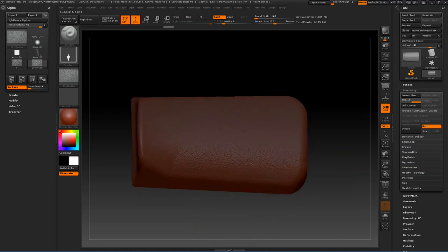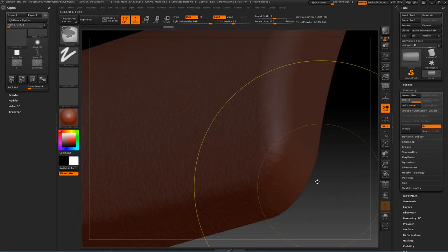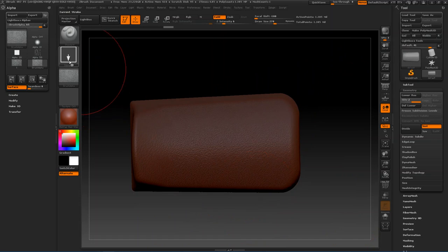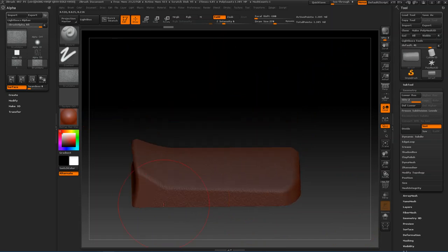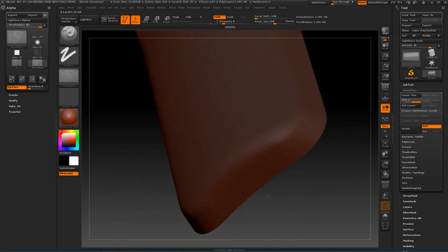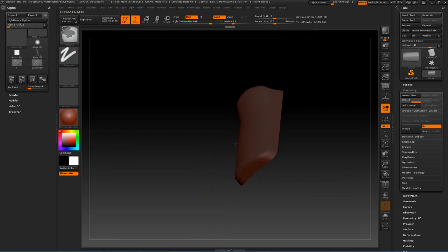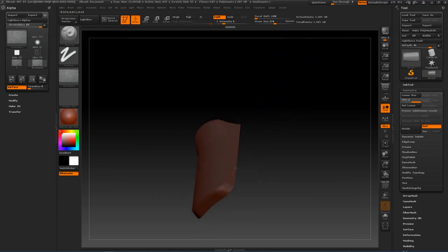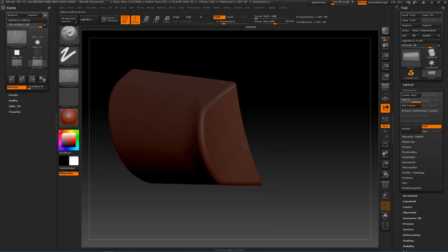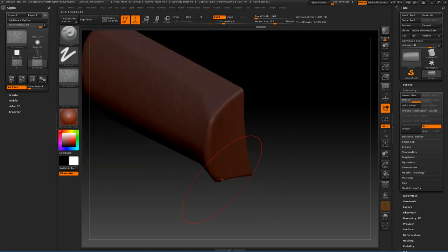And so now you can see it's textured over a lot of the part, but on some areas it's getting stretched. It is just projection. And so to fix those areas, I'll change my brush back to the freehand brush, and then just paint over some of the more problematic areas, some of the more difficult ones. You can zoom in, look at the corners on things. Just paint that all in there. Get the front side. And you can change the texture size by changing your brush size. So the bigger the brush, the bigger the texture for the most part.